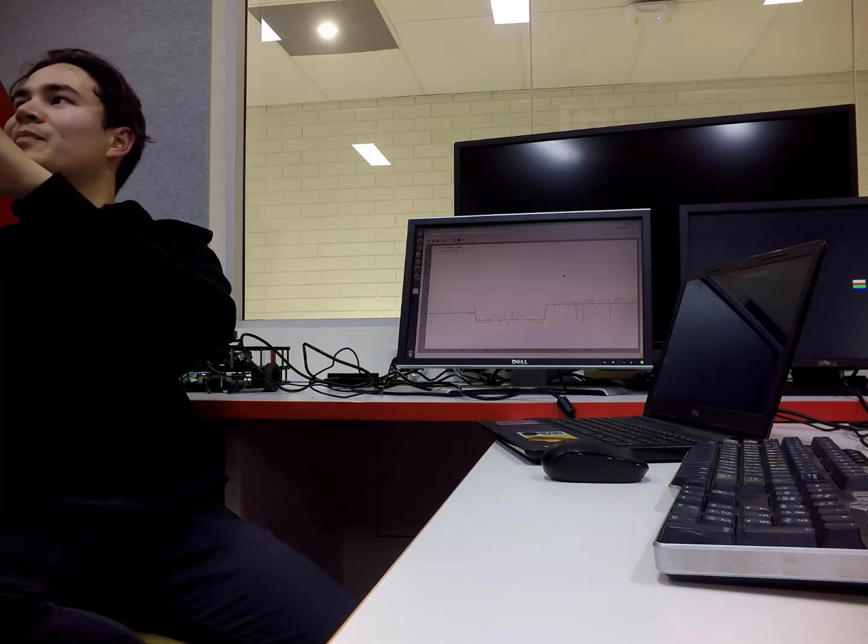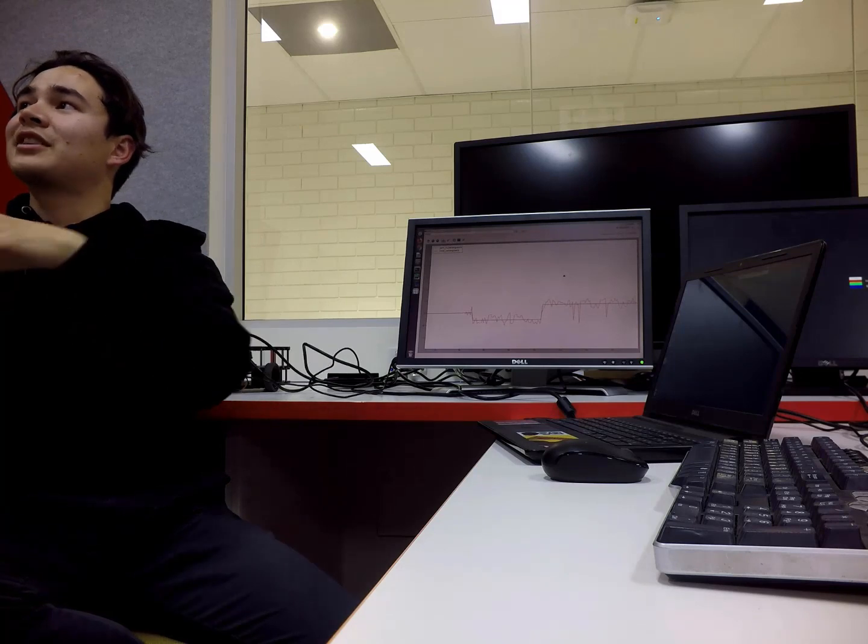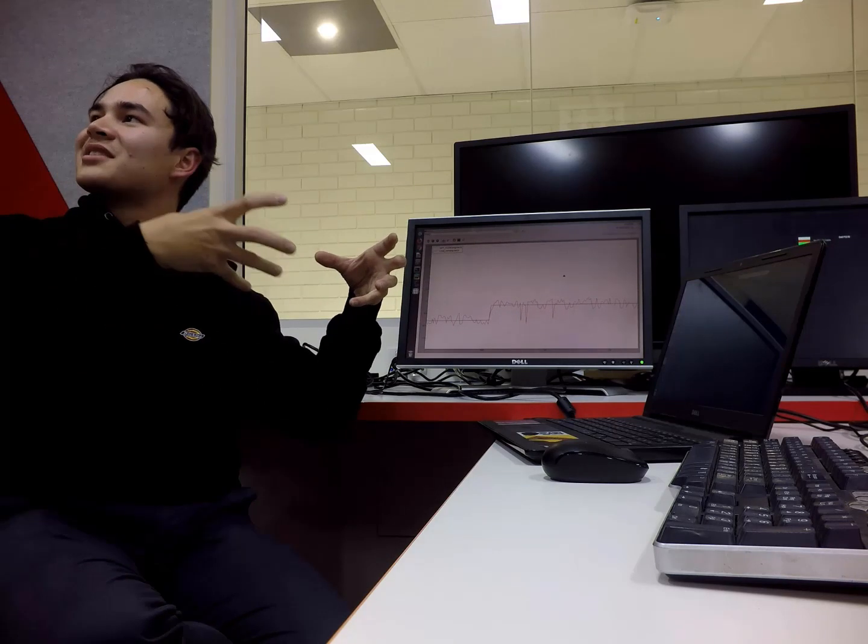So what you were asking before, if it has a history: for every 5 frames, it will calculate the distance and the velocity for each of those 5 frames, and then average that, and output that average velocity. Then we get rid of those 5 frames and take the next 5. It's not constantly stored, because you would probably run into the problem that if you were moving really fast and then started moving the other direction, it wouldn't map that as quickly because it would have a weighting towards the previous.